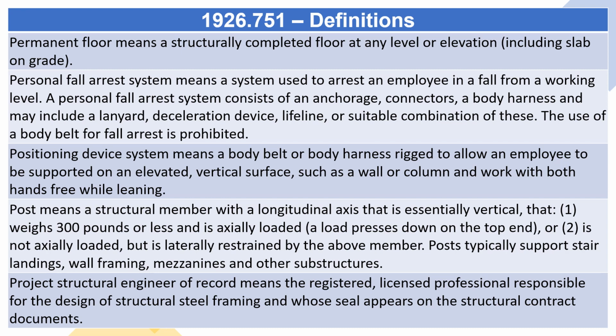Post means a structural member with a longitudinal axis that is essentially vertical, that 1. Weighs 300 pounds or less and is axially loaded, a load presses down on the top end, or 2. Is not axially loaded, but is laterally restrained by the above member. Posts typically support stair landings, wall framing, mezzanines, and other substructures. Project Structural Engineer of Record means the registered, licensed professional responsible for the design of structural steel framing and whose seal appears on the structural contract documents.